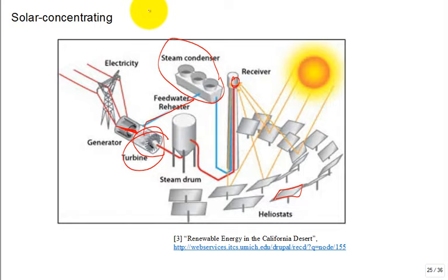Or a cooling tower where you have water. We reject a lot of heat into the atmosphere at UTSA on the campus with cooling towers, where we're spraying water in and using evaporative cooling. But you have to provide makeup water. And now the value of water has gone up, and so a lot of states want people to just reject the heat into the air without evaporation. It's less efficient. Engineers like the evaporation. We like the water, but hey, we'll do it without evaporation.